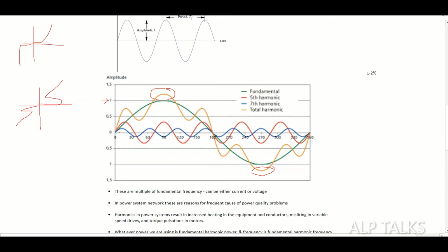But say if this supply is given to a motor, what happens? Will the rotation be smooth? No. Here you can see the rotation is pulsating. These things are not suitable for many industries like the paper industry. For example, one motor is running, taking the paper roll. Whenever these types of disturbances are there, that roll will be disturbed, right? That may break down here. The paper may break. So quality problems will be there.